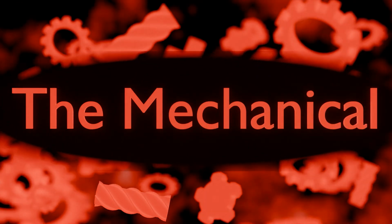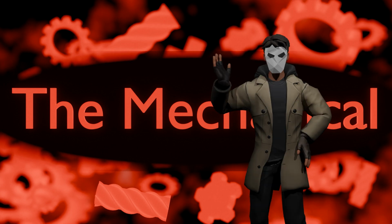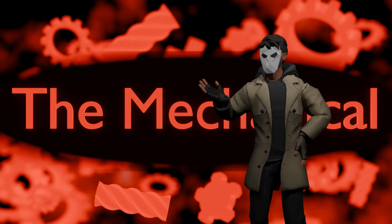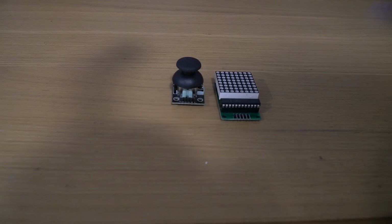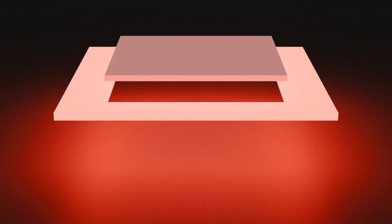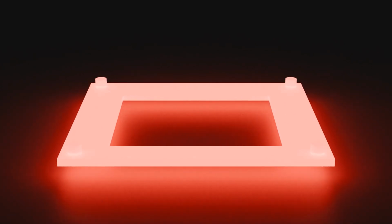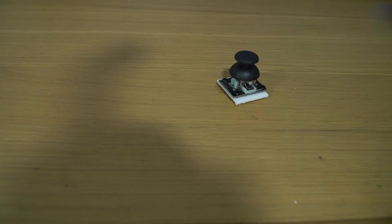the mechanical. And for the mechanical, there aren't really that many mechanical components in our controller. I mean, the main one is the joystick, and that's kind of already pre-assembled. But there are still some important things to note, and that's how are we gonna attach everything? And the answer to that is these circles on the corners. Basic idea is simple. We'll just start with a cube, we will flatten it, change the proportions, remove the middle to make space for the pins, and add the holes in the corners like so. Now we can just pop the screws into all of these and attach, for example, the joystick.